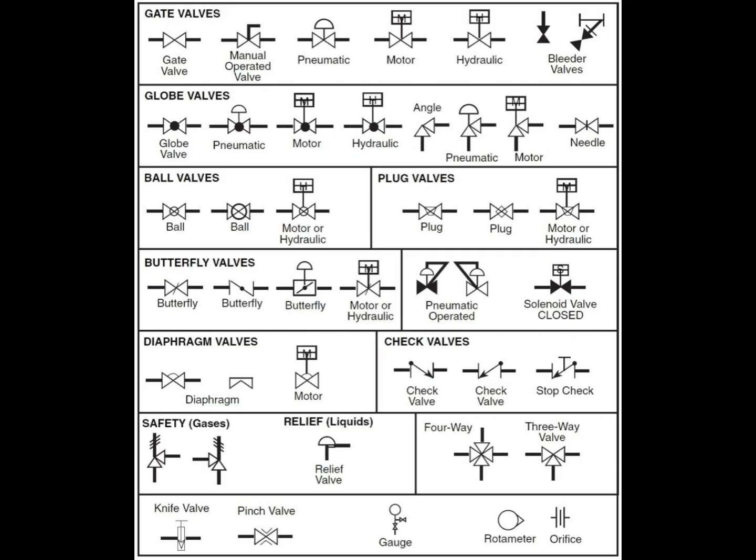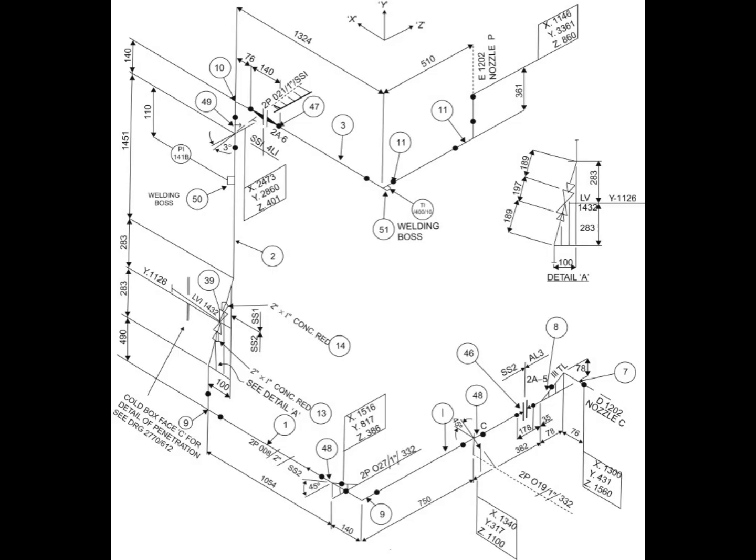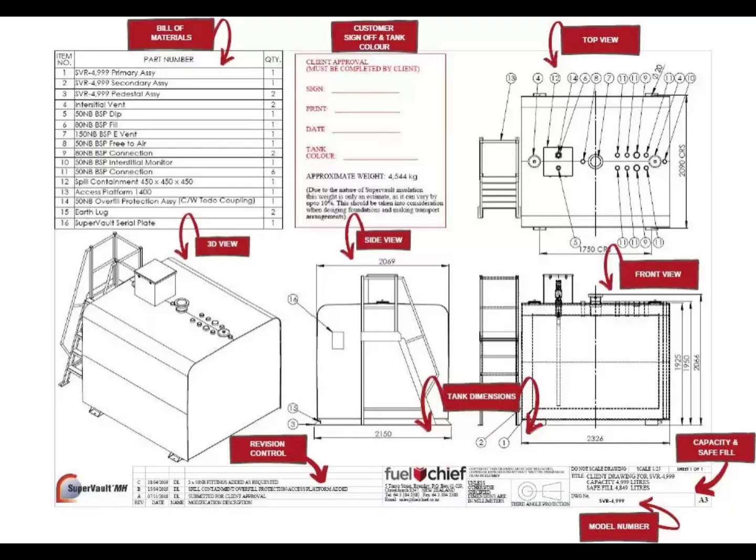Step 2. Read the drawings like an engineer. Never start measuring immediately. First, read all general notes, legends, and standard details. Understand the system purpose, flow direction, and operating intent. Identify equipment tags, line numbers, materials, and design standards. This builds a complete mental picture of the system before any quantities are extracted.